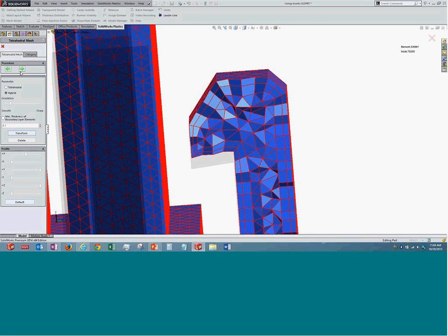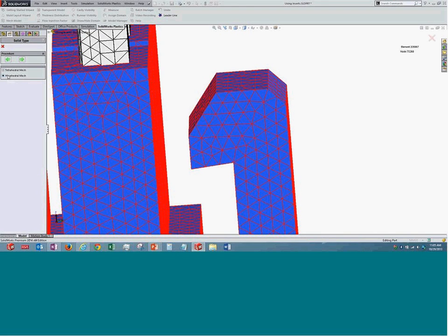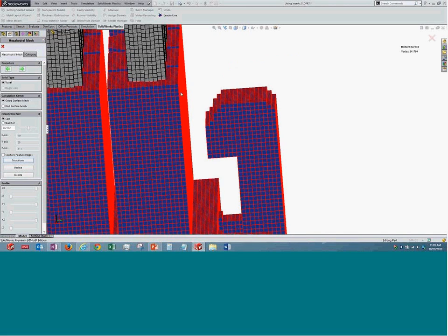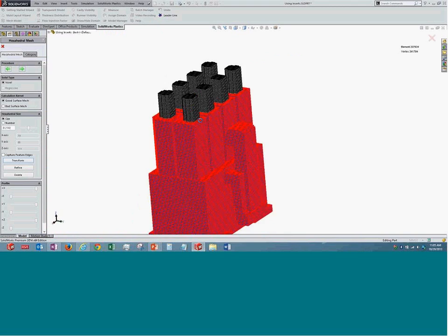So mesh into a hexahedron. The hexahedral mesh looks like it is filled with hexahedrons. We decide on the size and the other details. I would like to keep this a hybrid and proceed with the analysis. Let me do that and move to the next step. So this would be the extra step that we are doing here, wherein we are